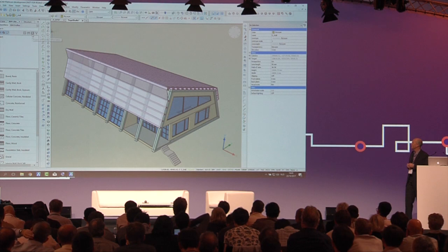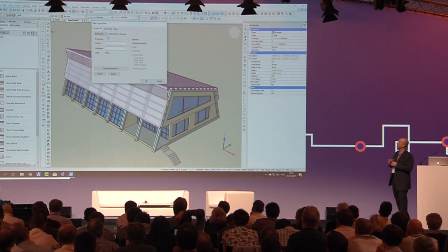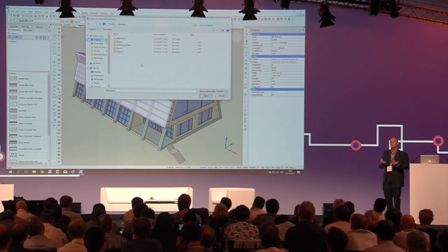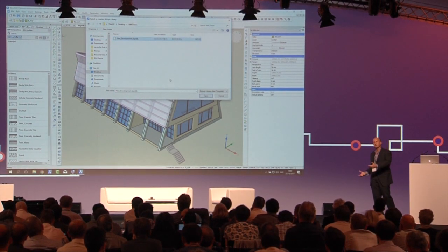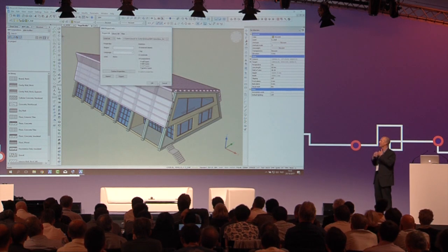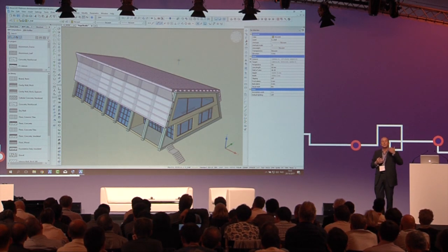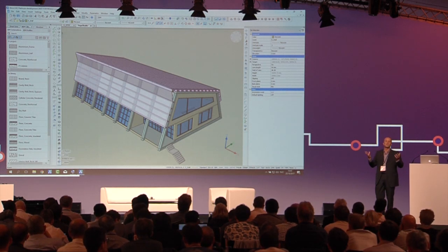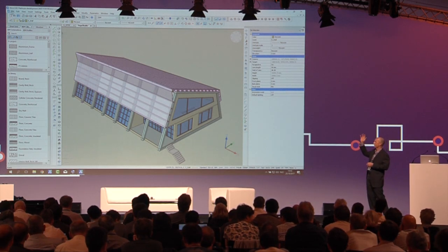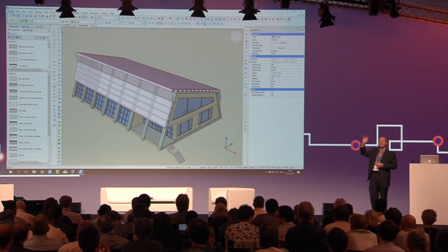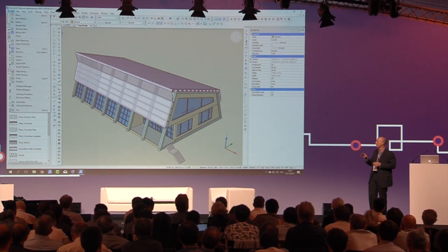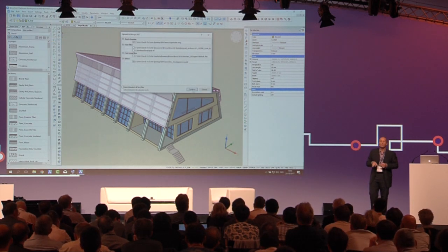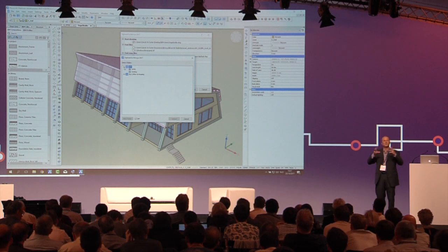So now, when we first set up these models, what Jacob's doing is switching it from an embedded database to point to an external database. The reason that we're doing that is so that when we upload it to 24/7, there's a central library that's maintaining all the information about the classifications, the buildings and stories that have been created. And so when we upload this to 24/7, which we're going to do, it'll bring all that data and information together.